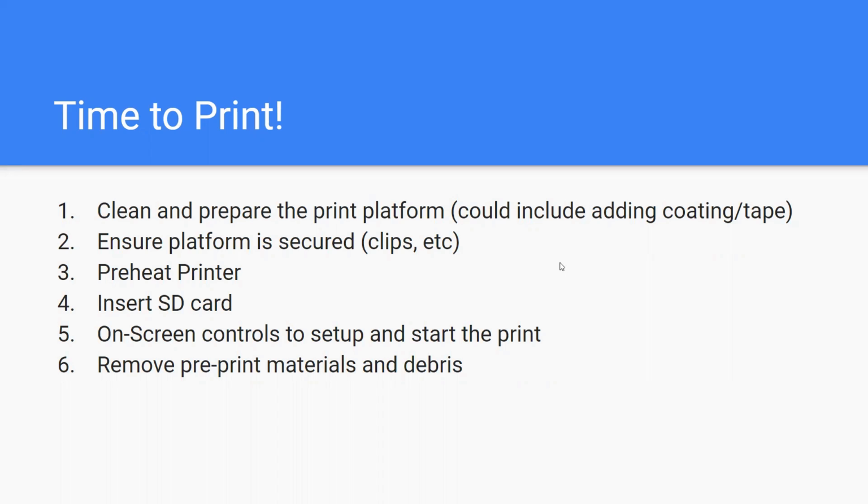So what I highly recommend is adding coating or tape. Blue painter's tape works great. I've seen that most commonly. And yeah, ensure that the printer platform is secured. So there's going to be clips for that. It's pretty simple. I have seen times where it's not been secured.